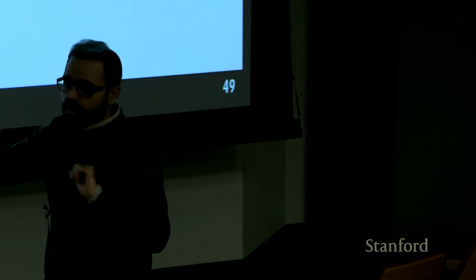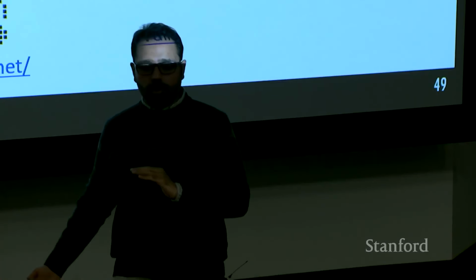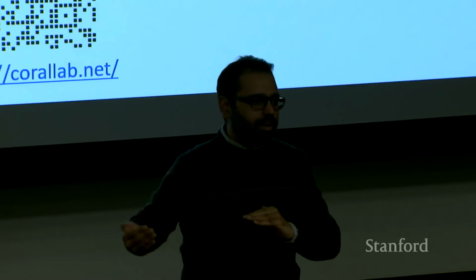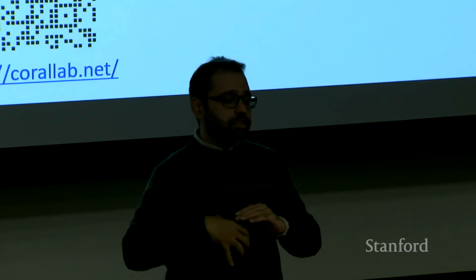But there is an inherent issue there. A lot of current work, like in imitation learning, is solving this problem in workspace. There is no guarantee that you can map this trajectory into a C-space trajectory. Your robot may run into local minima. Oftentimes, if you are performing very complex tasks, you don't have a direct mapping from the workspace trajectory to C-space.